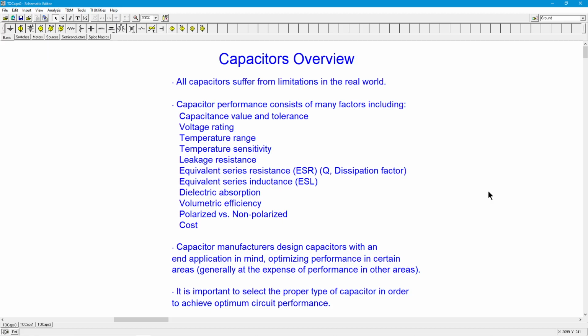You would expect it to stay at 0, but if something has high dielectric absorption, it will sort of rebound, almost as if you could mentally think of this as like sponge rubber, like you squeezed it down and then you let go of it and it slowly re-expands. So you could have a dielectric absorption that's 10%. And what that means is if you had a capacitor charged to, let's say, 500 volts, and it's got 10% dielectric absorption, when you discharge this thing down to 0, it can rebound back up to 10% of that 500.